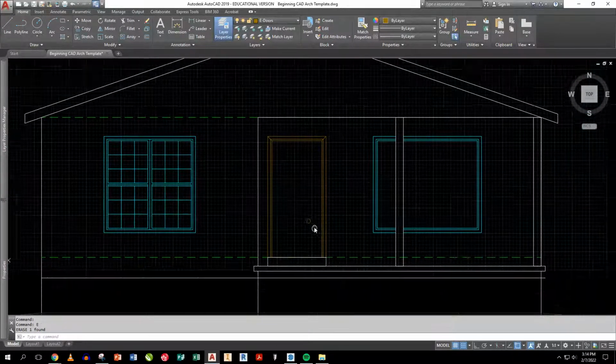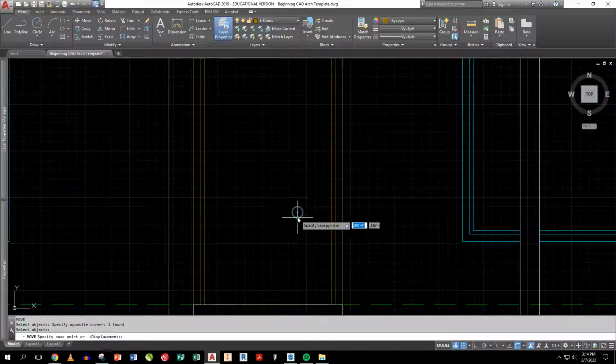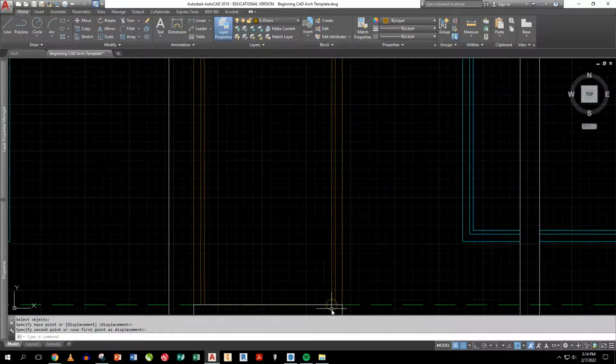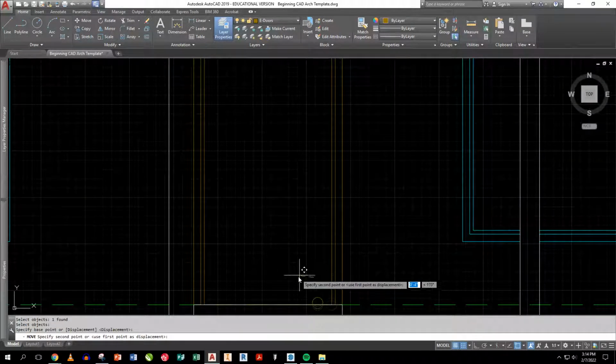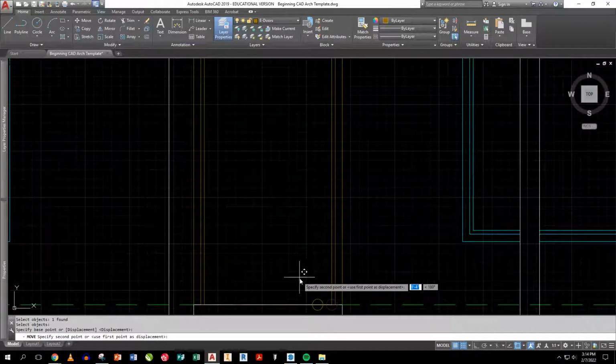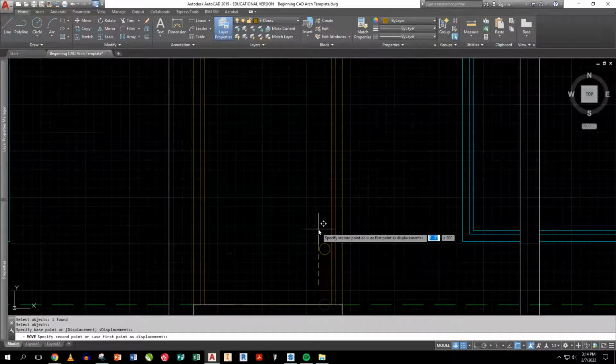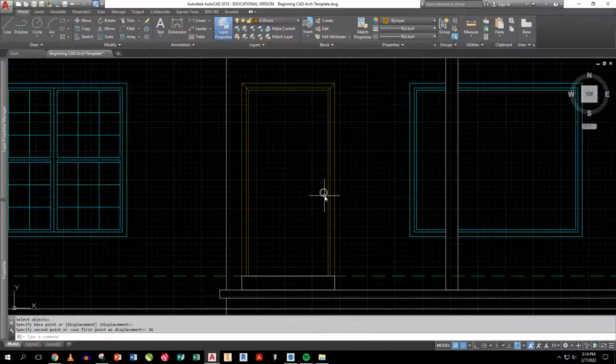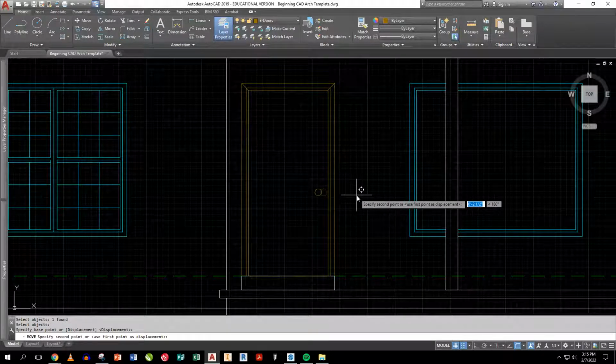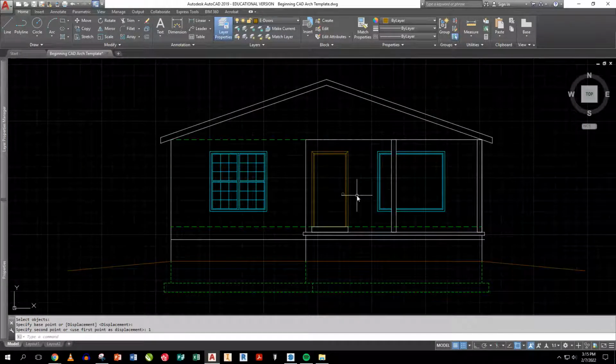That looks a little better. Okay, and then I put it on my house and I literally just say, okay, let's see where it's going to fit. Honestly, most doorknobs are over about an inch and a half, well, it's kind of 2 inches over for this, and they're 36 inches up from the floor. So that's about where it sits. If it's too close to this jamb here, I'll move it another inch or so, but that's where the doorknob's going to sit, most probably. And it doesn't have to be perfect because you're going to actually specify the door, unless you want to draw the actual door and then go look it up.